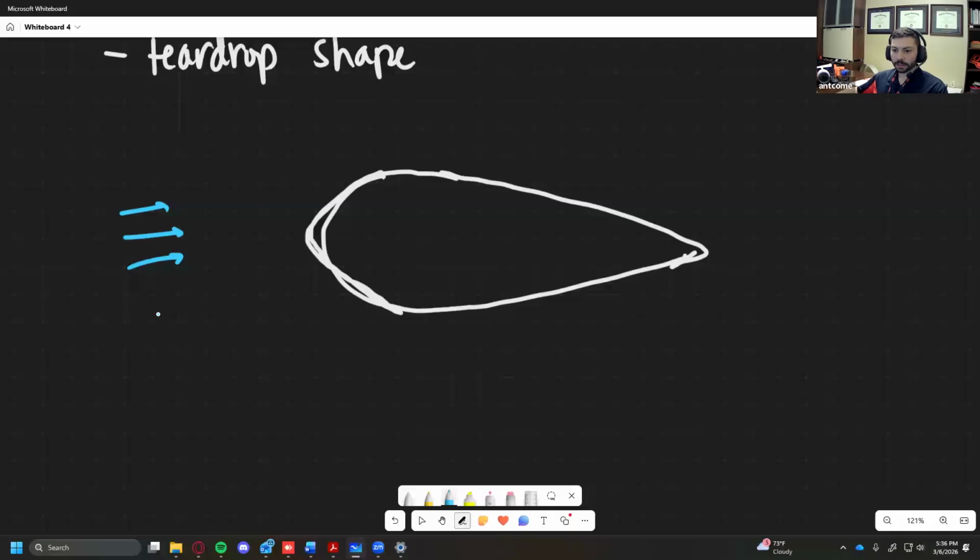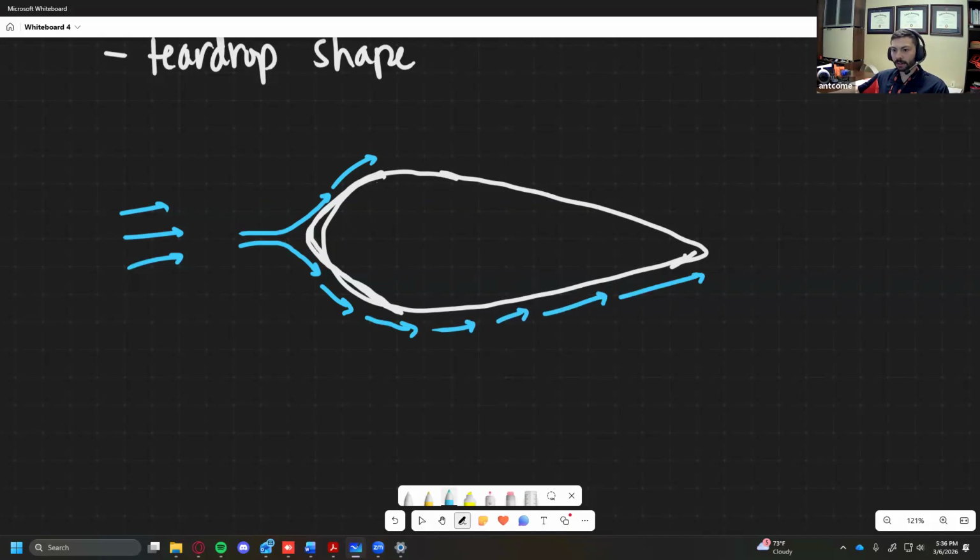So we're trying to divert the flow smoothly so that the angle doesn't go 0 to 90. We can go 0 to maybe 30 or 0 to 40, something the flow can turn around more easily. And because this isn't such a sharp fall off, the flow can stay attached all the way around this teardrop, all the way until it falls off.